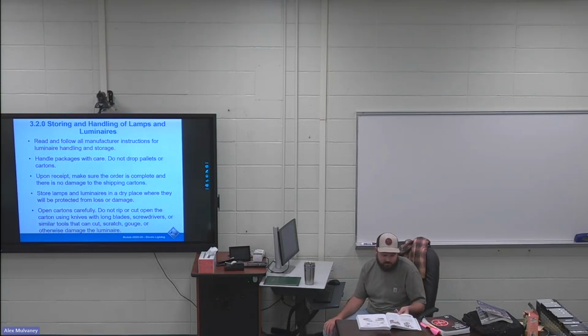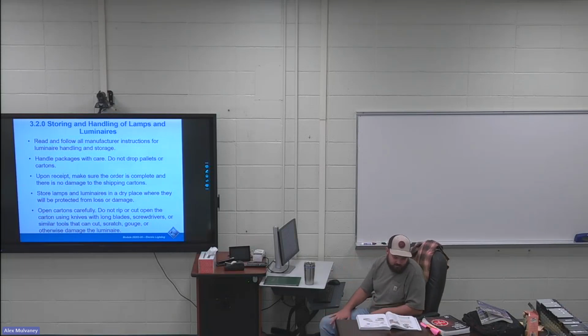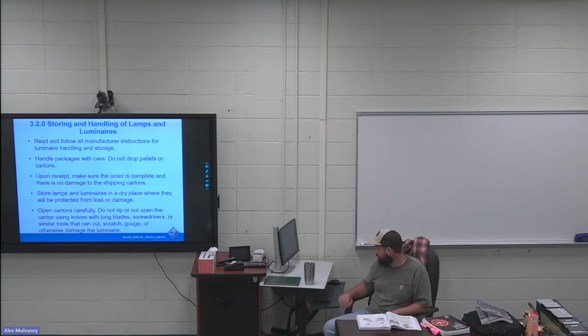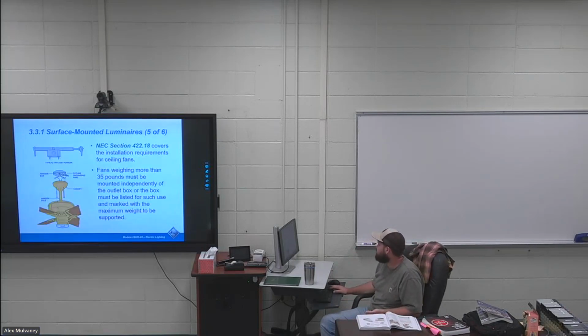Going into pages 36 and 37. On page 36, this is recessed luminaires. First paragraph, second sentence is highlighted. Properly supported outlet boxes are placed above the ceiling and separated by a minimum distance of at least a foot. These recessed luminaires are separated by a foot. So they have some of the rules up there in the top right on page 37.